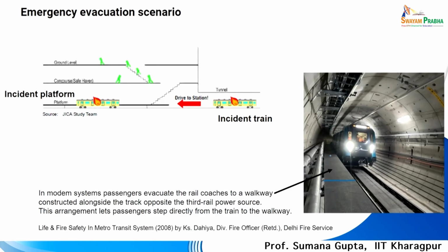At that level the doors will be opened and the people can come out and walk to the nearest railway station. So, these kind of things are getting built into the underground metro stations for evacuation scenarios. So, these are to be known to an architect if at all they are designing or getting the opportunity to be a part of a metro station design process.